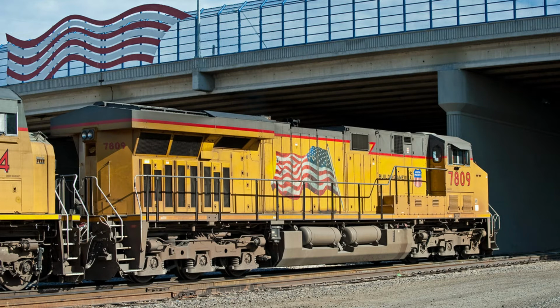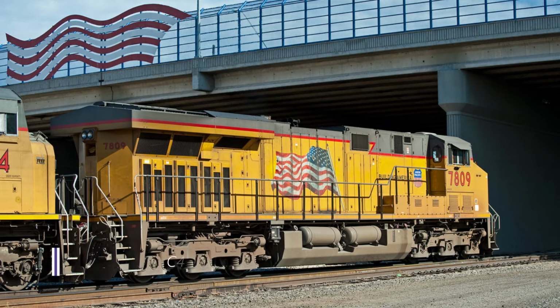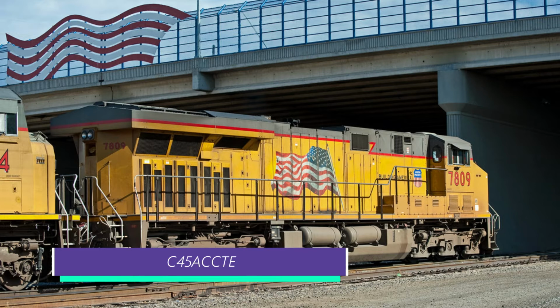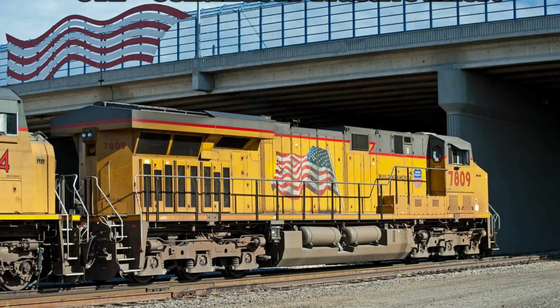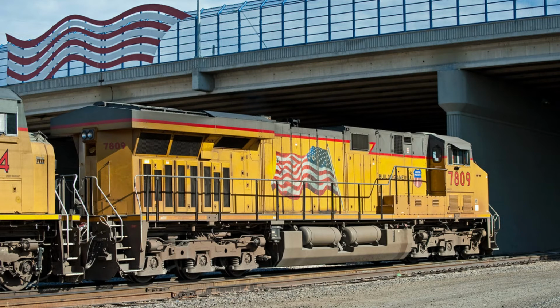This locomotive is usually called the ES44AC, but UP refers to them as a C45ACCTE. The C means the locomotive has 6 axles. 45 is the model series because the locomotive has 4,400 horsepower. The A and the C mean the locomotive has alternating current traction, and then the CTE is continuous tractive effort. So if you see one of these GEVOs or AC44s with the CTE at the end, it should mean continuous tractive effort.